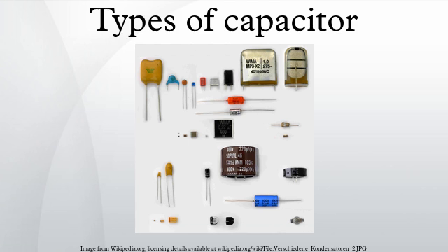Large capacitors tend to have higher ESL than small ones because the distances to the plate are longer and every millimeter counts as an inductance. For any discrete capacitor, there is a frequency above DC at which it ceases to behave as a pure capacitor. This frequency, where XC is as high as XL, is called the self-resonant frequency. The self-resonant frequency is the lowest frequency at which the impedance passes through a minimum. For any AC application, the self-resonant frequency is the highest frequency at which capacitors can be used as a capacitive component. This is critically important for decoupling high-speed logic circuits from the power supply.